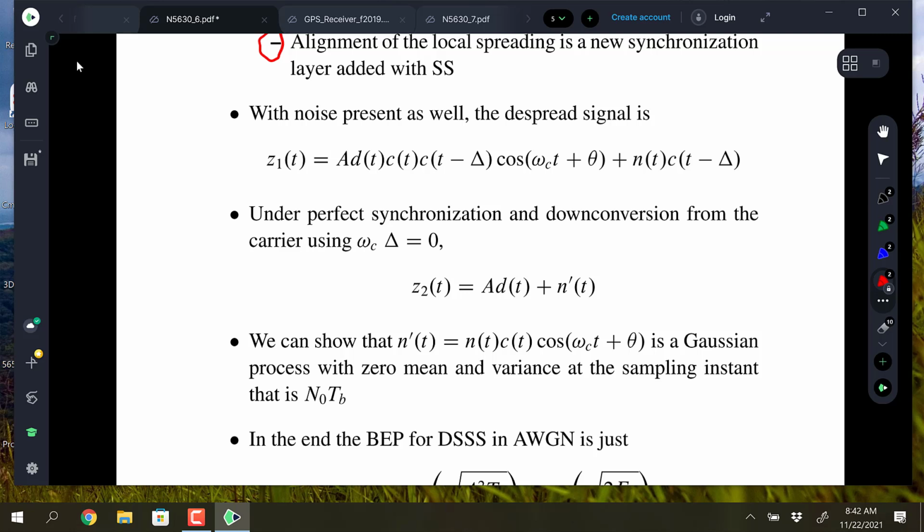That's the tracking side of it. It's not the tracking loop, it's the Kalman filter side of it, where you're actually getting position estimated. And in that particular model, I use SGP4, which is one of the propagators available for Python, a satellite propagator, so I can put up the ephemeris information for the GPS satellites from back in time, from the sample that I ran. And then you can propagate the satellites and do all that stuff too. We'll maybe look at that too, because that is a GitHub project that's out there.